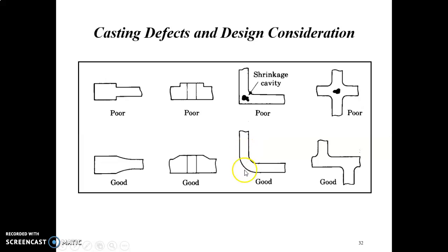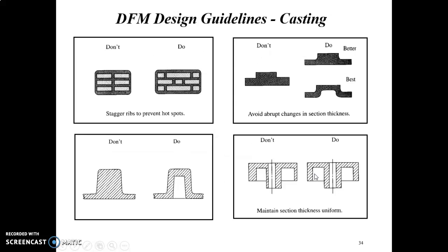Okay, so this is the better design. Stagger it to prevent hotspots. Avoid abrupt changes in section thickness and maintain uniform section thickness.